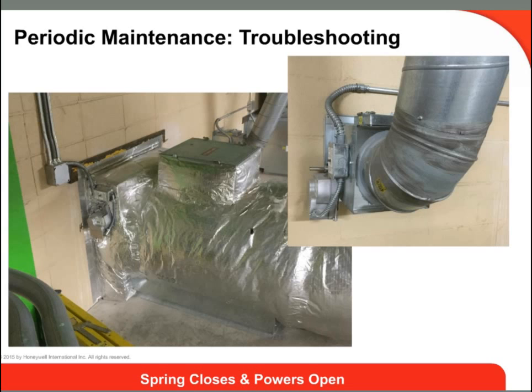If the actuator does not drive open or drives open but will not spring close, replace the actuator. If the damper does not smoothly operate when the actuator is removed, the damper may need to be replaced.